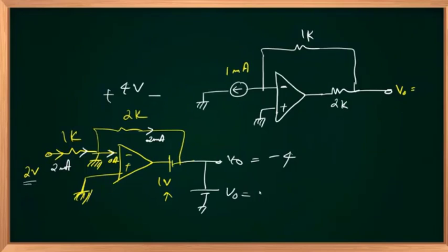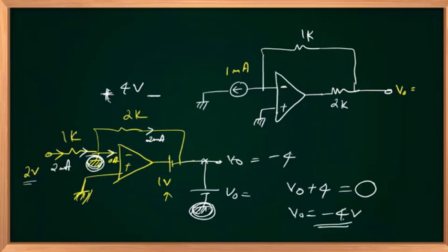In that case, you can identify the current, you can identify the voltage. This point voltage with respect to ground is asked. This is at ground, this is also at ground. So I'm starting from here, negative, positive. I'm taking it as positive out. This is negative, positive again. So I should take plus 4. And I have started from ground, I have ended at ground. The sum should be equal to 0. It's a closed loop. Implies V out equal to minus 4. That's it. Very simple. Right.